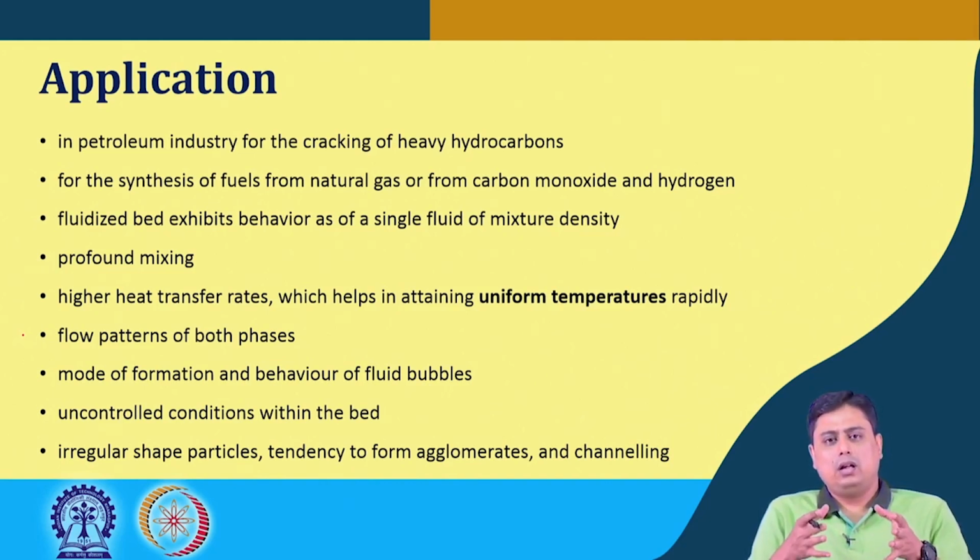This irregularity in results for a particular application comes from uncontrolled conditions within the bed, and that stems from the irregular shape of the particles, their surface property, their orientation, and the non-uniformity of fluid distribution at the inlet, which propagates along the bed.